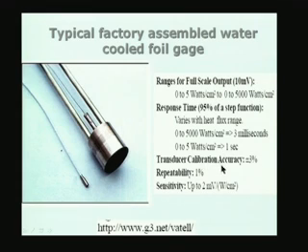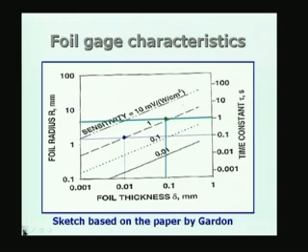So, transducer calibration accuracy plus or minus 3%, repeatability 1%, sensitivity can be as high as 2 millivolts per watts per centimeter square. If you go back to the figure we had earlier, here you can see we are talking about the region between 1 and 10. Sensitivity is 1 here, is 10, somewhere in between 1 to 2 is very easily obtained.